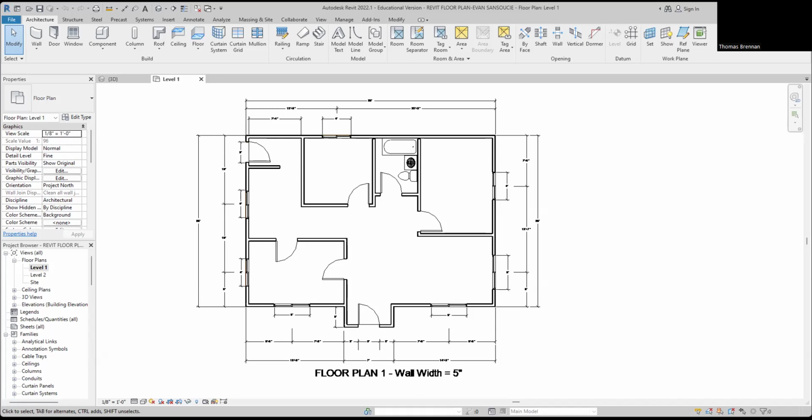So you get your 1/4 inch scale here. The 1/4 inch scale is going to be right here. Now, I'm going to take this and just show you how this works. Whenever you work with these scales, you always orient it from the 0. First of all, it says 1/4 inch right here, and then this is 0. That's the first one here. And then there's a little scale.